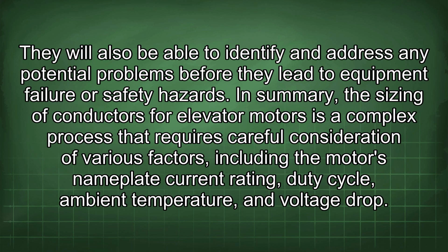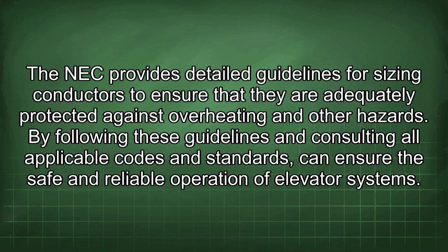They will also be able to identify and address any potential problems before they lead to equipment failure or safety hazards. In summary, the sizing of conductors for elevator motors is a complex process that requires careful consideration of various factors, including the motor's nameplate current rating, duty cycle, ambient temperature, and voltage drop. The NEC provides detailed guidelines for sizing conductors to ensure that they are adequately protected against overheating and other hazards. By following these guidelines and consulting all applicable codes and standards, you can ensure the safe and reliable operation of elevator systems.